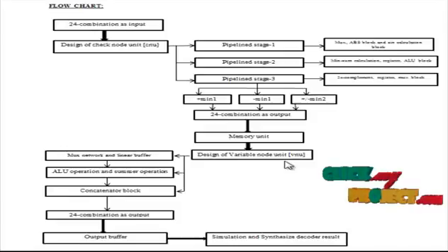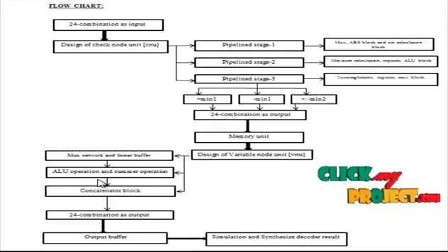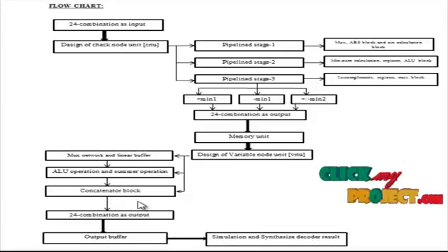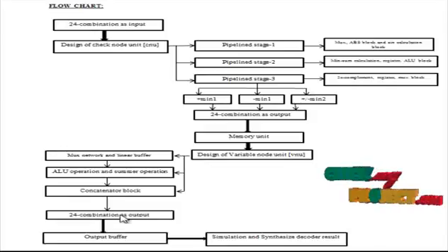Then following this VNU, memory register elements are used. In the memory architecture, the high throughput LDPC decoder has a memory unit to store 24 combination inputs, and it is also used to read and write the 24 combination inputs in memory. The RAM memory is used to read and write the 24 combination of input in 5 bits in the high throughput LDPC decoder. In the LDPC memory architecture, the input is provided from the CNU block and the output data stored in RAM memory is given to the VNU block. Finally, the LDPC decoder consists of CNU, VNU and the memory architecture to provide highly efficient decoding operation in the wireless standards.